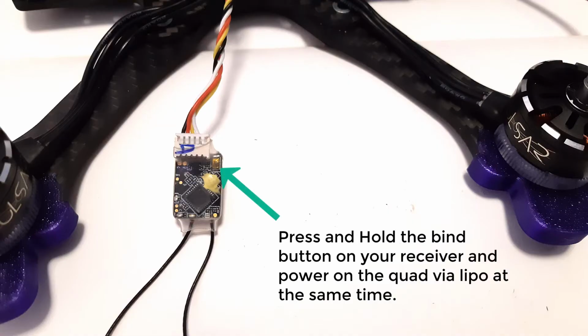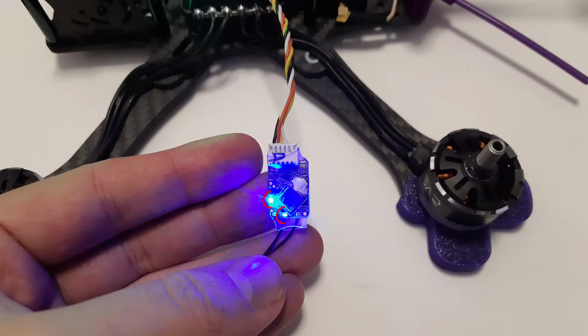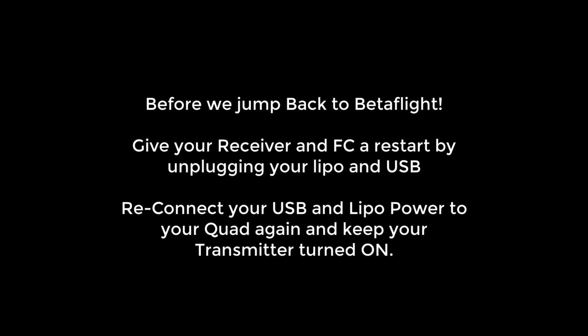An easier way to do this binding process, if you find it difficult to hold the RXSR because it's such a tiny receiver, is to use a pencil tip or some tweezers to hold this while you plug in the LiPo. You should see the blue and green light turn on like so, and we're finished.